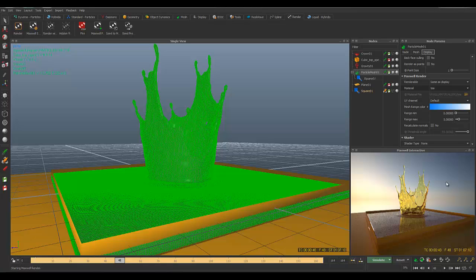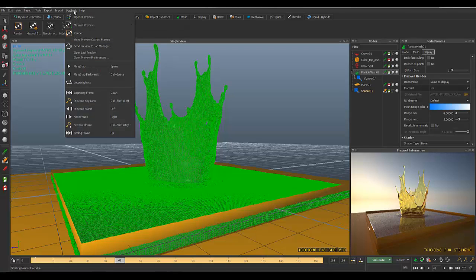And if you want to make a preview from Realflow, you can go to playback and click on OpenGL and Maxwell Preview. If you click on Maxwell Preview, it will give you this just like this interactive rendering. It will render the sequence with a shader.